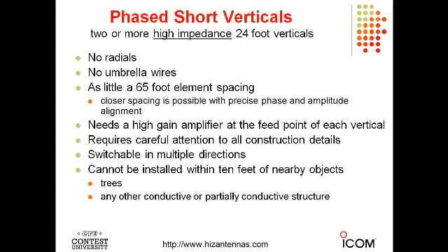The biggest difference is for the high impedance verticals, you don't need radials, and for many people that's important. You don't need any umbrella wires to help to resonate the antenna, because the high impedance verticals are non-resonant, whereas the low impedance ones are.